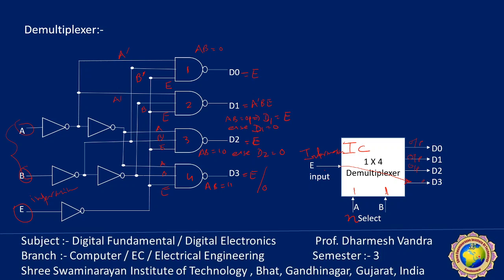While all other outputs are maintained at one, because the decoder and demultiplexer operations are obtained from the same circuit, the enable input is what makes the circuit a demultiplexer. The decoder itself can be used as an AND, NAND, or NOR gate. So I hope it's making sense how the circuit's output can work in different conditions. Remember that the decoder and demultiplexer can be constructed together.